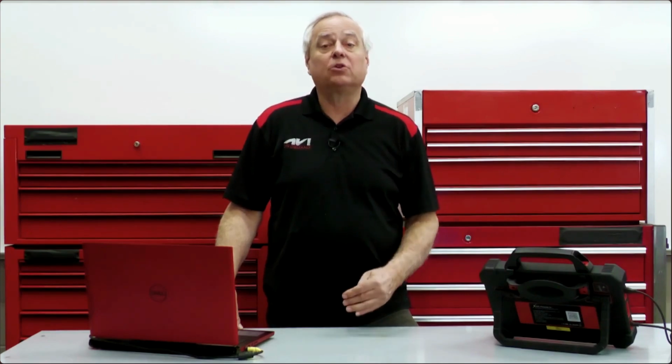Now, it's not uncommon in today's world to get 2 or 3 updates sometimes within a month on a particular vehicle package. So it's always a great idea to get on a regular, normal cadence with your updates. Now, 2 things are important on updates. Number 1, pick a day. Monday night might work very well. You're back from business over the weekend. When you close down the store on Monday, hook your scan tool up for updates. Let it run the updates when you leave that night.